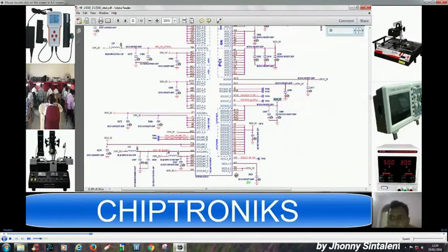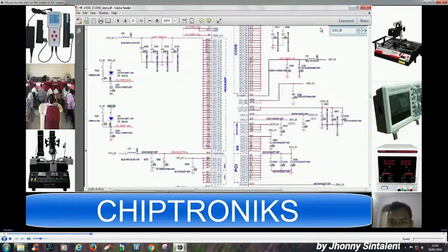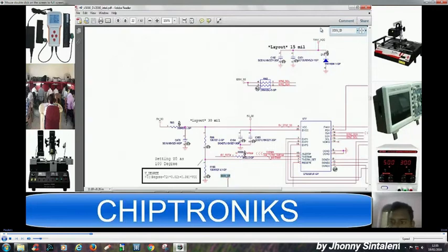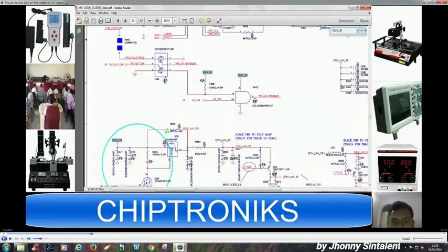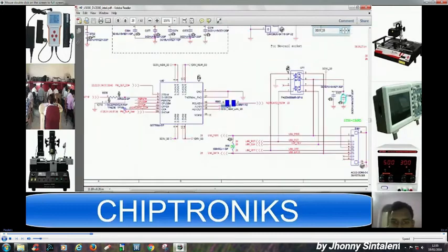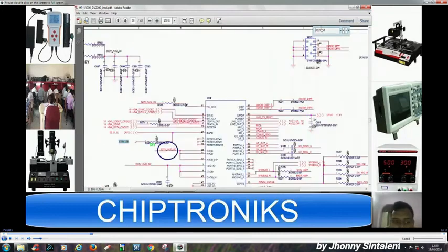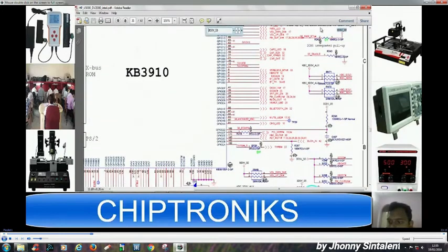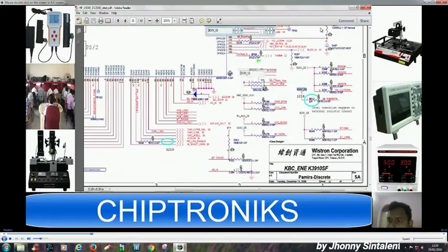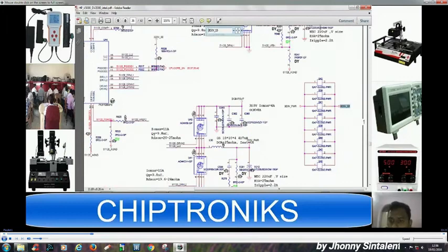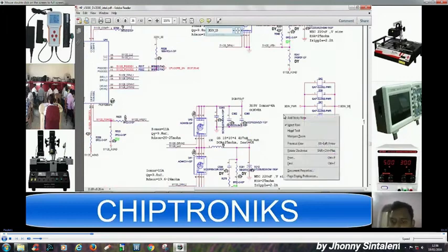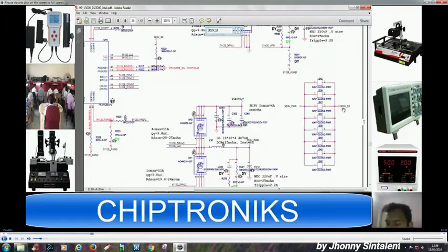3D3V_S5. So we'll check from where this 3D3V voltage is coming. We'll select this and we'll just paste it out. We'll see from where this is coming, right? Now obviously it would come from the 3V 5V regulator IC, but we are checking how it is coming. Now you can see 3D3V_S5 is generated from